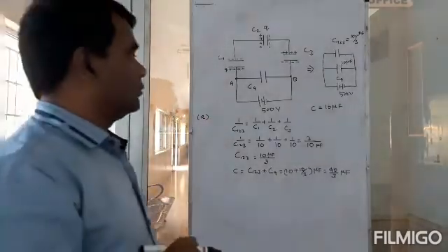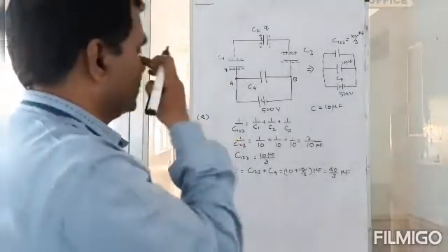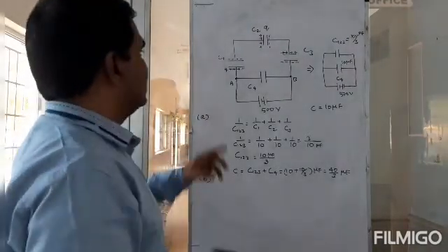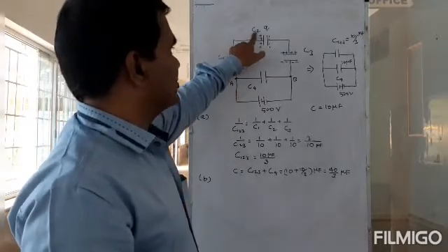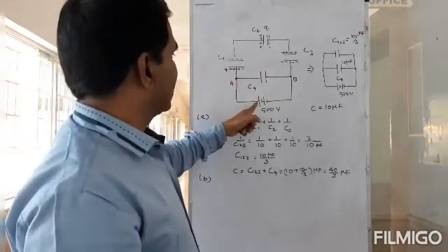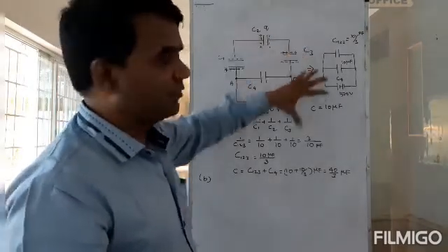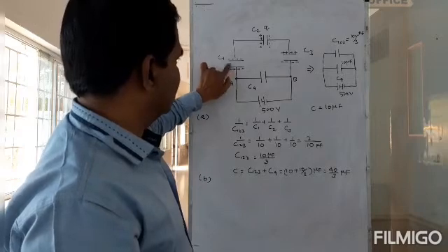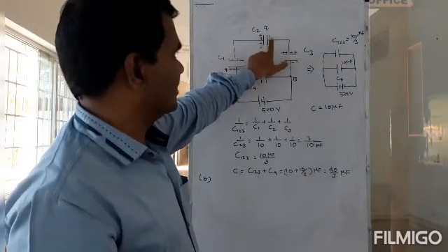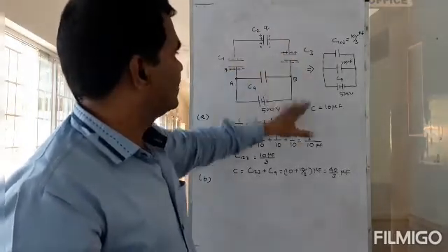And what is part B? Part B is the charge on each capacitor. Well, that is actually easy, because you see the charge on C1 is the same as the charge on C2 and the same as the charge on C3, right? So the battery will put just one Q here, and that's about it. Then the other charges get induced. The moment it puts a plus Q here, then clearly minus Q accumulates here, plus Q automatically gets generated, then minus Q accumulates here, then plus Q automatically gets generated because of induction, single conductor activity. So you get this, right?